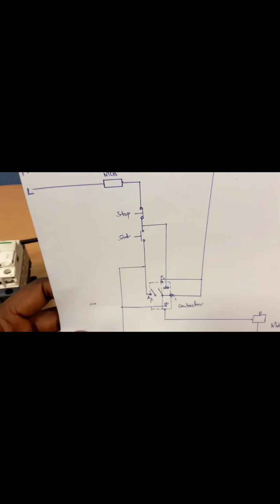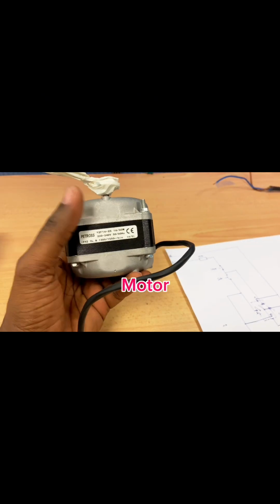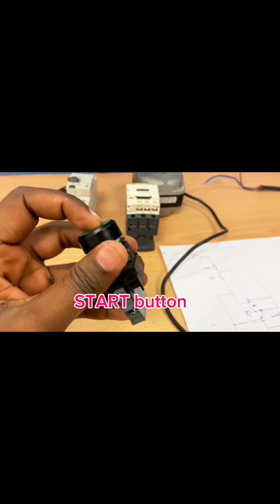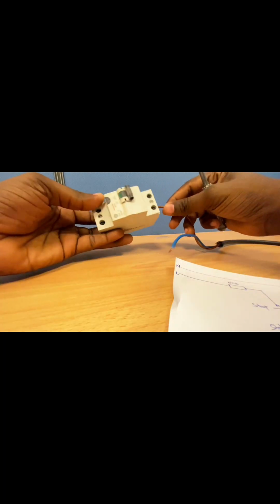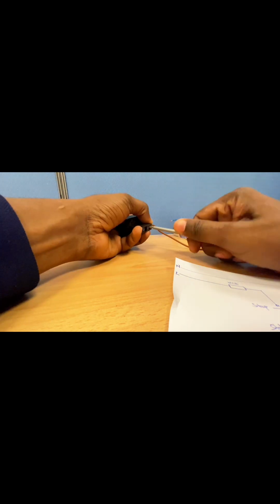Let's consider this simple wiring diagram to build a circuit for our project. Some of the key components we are going to be using: motor, contactor, MCB, stop button, this is our start button. Following our wiring diagram, our phase will pass through the MCB, then get connected to our stop button.